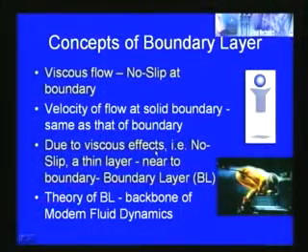This is important in aerodynamics, like a flying vehicle, airplane, or space shuttle. The boundary layer analysis is very important, since based upon that only we can design the airplane or the space shuttle, since the velocity variation is very important. But outside the boundary layer, we can approximate, and depending upon the flow condition, we can even consider it as a potential flow. So this concept of boundary layer we will discuss first, and then we will see some of the equations related to the boundary layer.